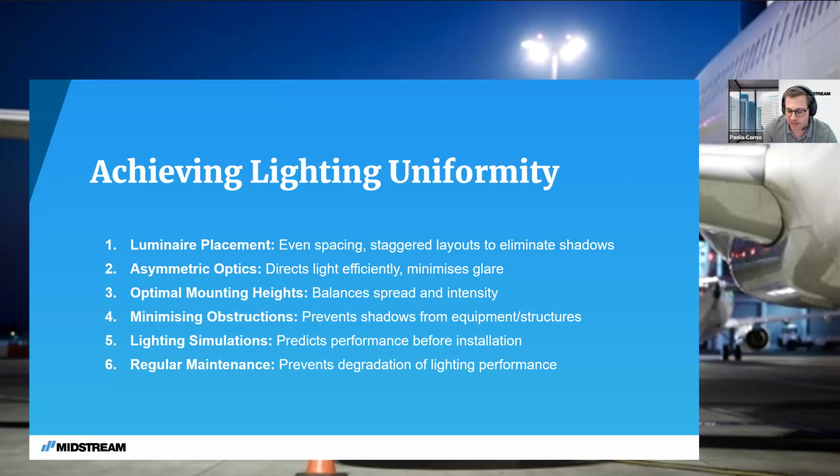When I mean well-developed, I mean something developed for this task. So with the right geometry in mind, of a ratio between height and angles of asymmetry of a luminaire, by using a good asymmetric optic, achieving uniformity both in theory, when working on the software, but also in practice, becomes much easier. When you have the right optic, you work with, say, a multi-layer approach. So you identify which way the luminaires have to aim, and you add luminaires to reach the light level.